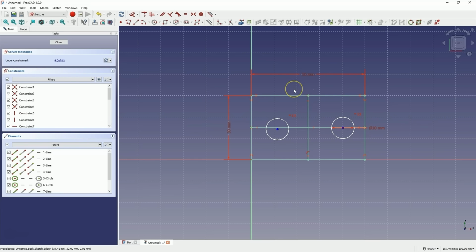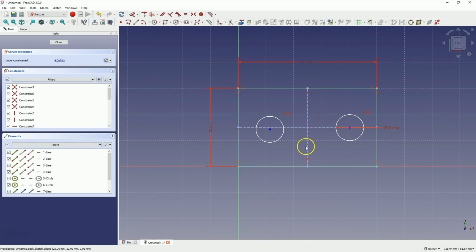And so, at this point, these geometries are the main sketch geometries and will participate in the creation of a 3D solid based on this sketch. In order for these geometries to be only auxiliary geometries, we need to change this geometry to construction geometry, and to do this we select these 2 geometries and choose the option to switch geometry to construction geometry. And now these geometries have changed color, changed their shape, and this means that these geometries are auxiliary geometry of the sketch. And now we constrain the circles to this construction geometry.